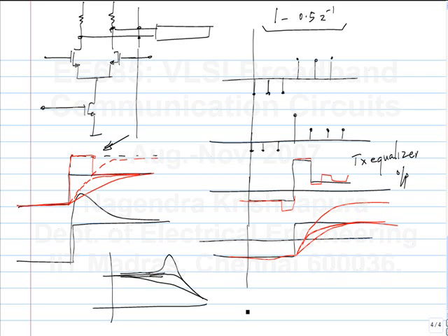No, I mean, it's a sort of continuous time implementation of the FIR response, which is discrete time, meaning the time domain is quantized into steps of Ts. So in that way, you can think of it as a discrete time transfer function. What I mean by discrete time transfer function is some transfer function that repeats every sampling frequency. But instead of z inverse, instead of working with samples, you work with the whole waveform, but then you have e to the minus s times Ts here. That is a continuous time implementation of the same FIR response.